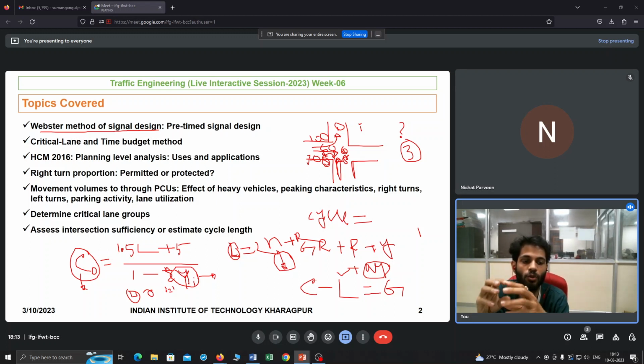I will give green. So how to decide the green time? Ideally all the vehicles along these three stretches have to pass during that green time. So how to ensure that? Now suppose your turning volume is 100, and you have something called a saturated volume also. What is the saturated volume? It is equivalent to the capacity of that intersection. Why is it called saturated volume? Because vehicles can traverse only during green time; it is not acting like an unsignalized intersection, where vehicles can pass at any time. Here vehicles will pass only during green time, right?